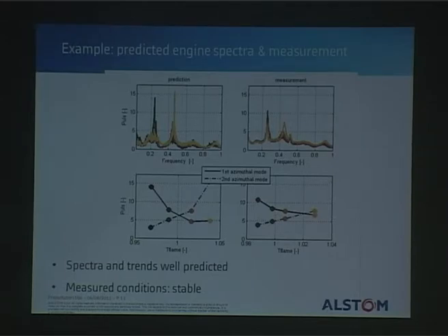But if you see its prediction, these are the spectra that have been predicted. It's a prediction, and here you see the amplitude of these peaks. Then you see different curves, and we changed the flame temperature. Now we collected the amplitude of this first peak here, and I plotted it over flame temperature. You see, this first peak, normalized, goes down with flame temperature. The second peak goes up with flame temperature.